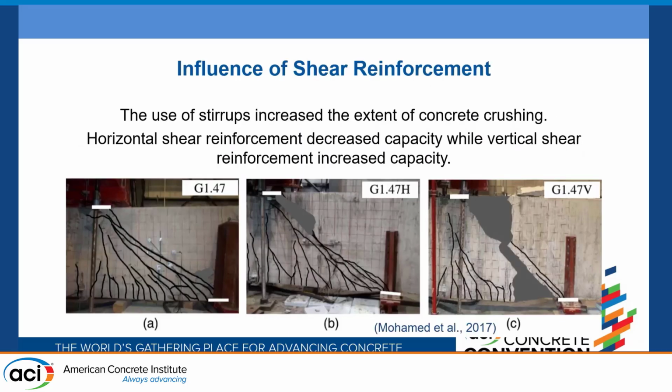And then another factor that Dr. Polak discussed was the influence of shear reinforcement. Here's one series of tests by one author, Mohammed et al., that looked at the same A/D ratio with different types of shear reinforcement. So this one in the middle had horizontal distributed reinforcement, and then this one over here